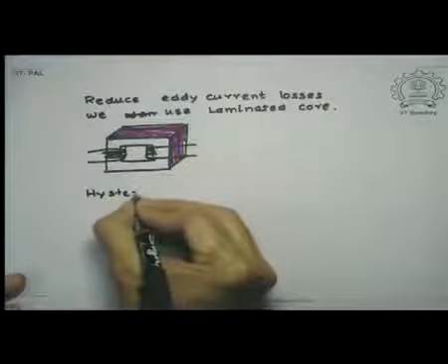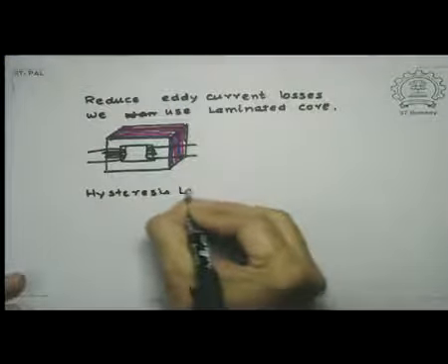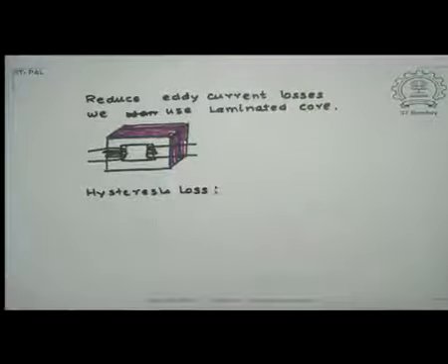The other problem which we have talked about is due to hysteresis. Now we have seen that hysteresis arises because of the remnant magnetization. Now in order to reduce it, I will not be able to go through the physics behind it, but what is done is to use soft magnetic material.